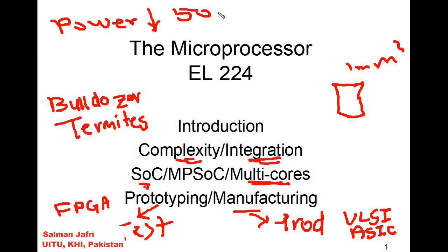When we are operating the cores at a lower frequency of 500 megahertz, the power consumption of those cores would be much less than if the cores were operating at a higher frequency of say 1+ gigahertz. So that is the idea. The multiple cores idea is also helpful in reducing the power consumption of systems.